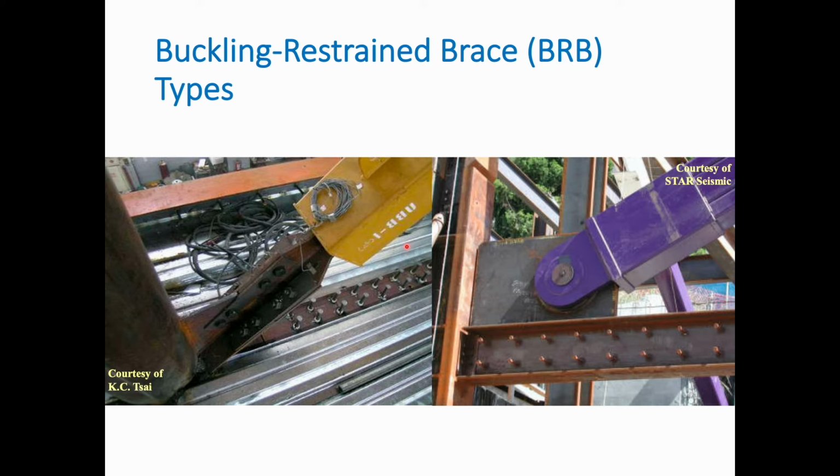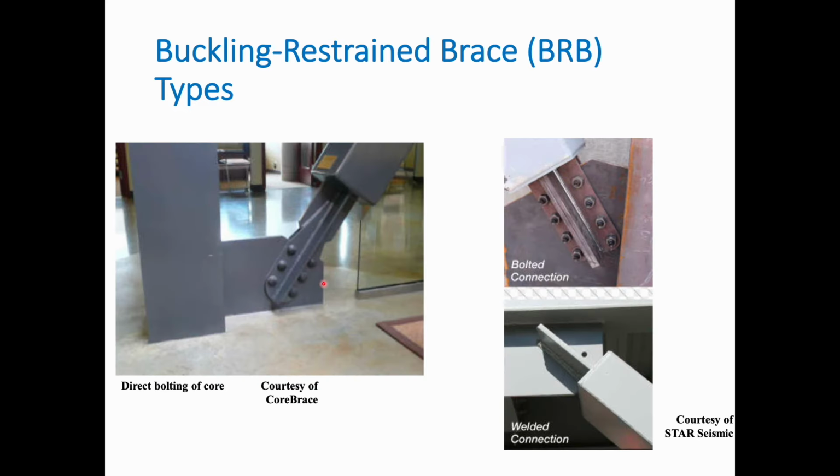We may use double angle sections with bolts, or a thick gusset plate with a pin to allow for the movement of the BRB system. Again, here, like before, gusset plate and fin plates with bolts or rivets. And in fact, what I wanted to show here is that the system design for the detailing is not much different to what it is for a standard brace system.